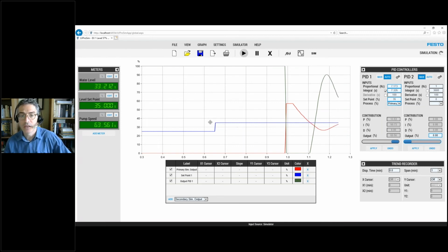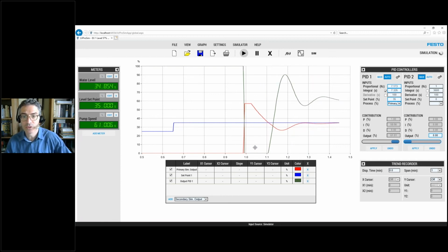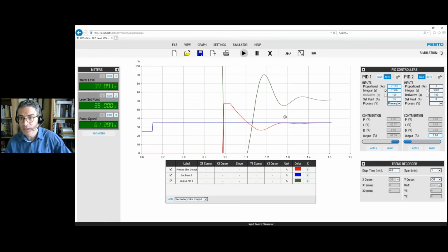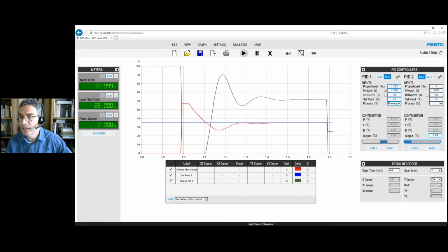As you can see here, we will have to restart that. But again, we have changed our set point. So let's say that the set point was changed here when we applied the simulator parameters. At that point, we had our controller responding by decreasing the output to 0, and the level here increasing really quickly. So you can see that we are actually getting to the set point really quickly. Let me do another change here back to 25 with these P and I parameters.